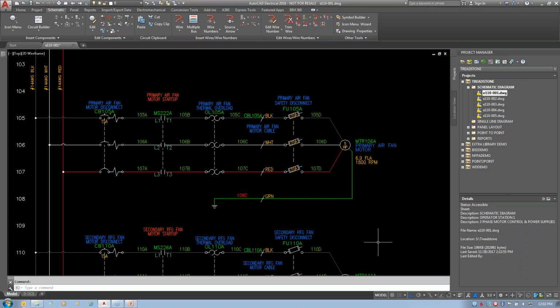So I'm going to be creating the 3-phase that's on here. It's just a redacted, simplified version of a 3-phase motor that I use in my training class. It's basically got a circuit breaker that's a magnetic instantaneous on there. It's got the motor starter, which is also connected to another drawing, a ladder diagram, and the overload cable marker, and the fuse switch in the motor.